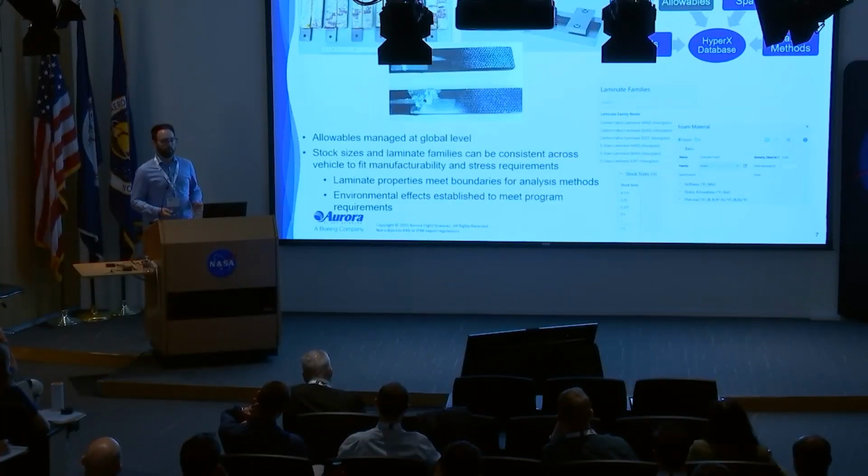So managing that at a global level ensures that people aren't going through and creating their own spreadsheets or making assumptions on what's B basis, what's A basis that we need to apply, and what are their stock sizes. Do we have any foam core thickness at our disposal, or are tooling constraints really limited to what stock sizes we have on hand or can machine at a low cost? Environmental factors also play a role here to help set the bounds for sizing and what your test data is as you go through. And you can make program level decisions on where you want to cut off things to make conservative or appropriate decisions at the stage of your analysis.